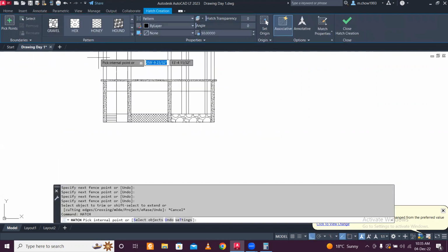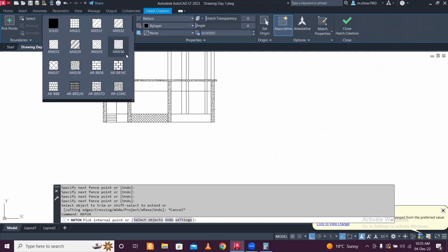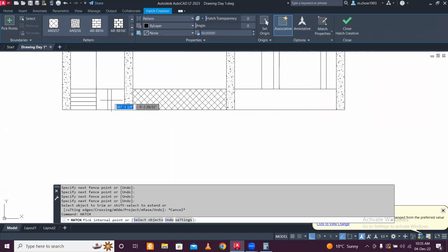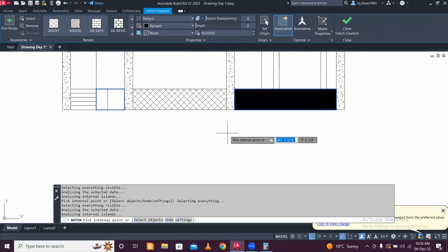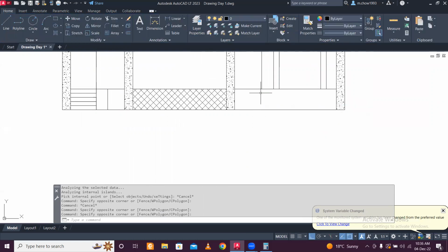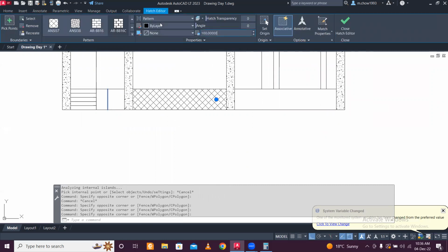And use the hatch. I'm focusing so much on the hatch because hatch is very important. So we'll use the sand version here, sand. Okay, not the sand, masonry, because there's no section. You see the masonry here. So brickwork, this seems fine. Okay, so select both of these, and then select this, and maybe we'll go 100. Point one. Okay, point one is coming as something. So let's go point five. Okay, yeah, coming close.